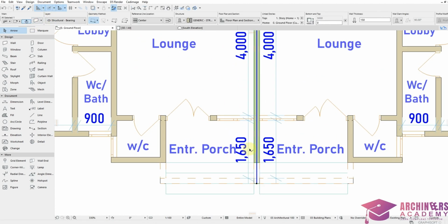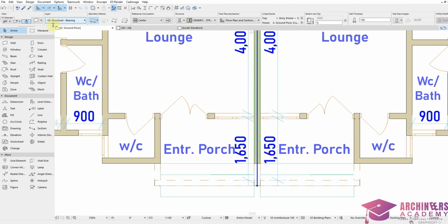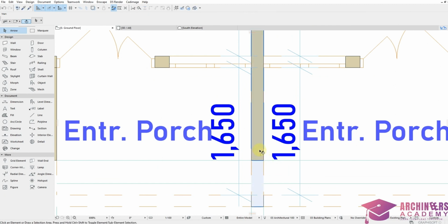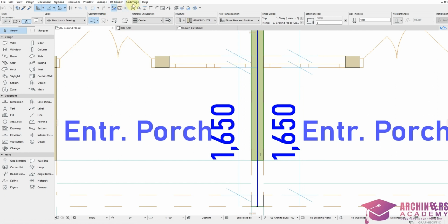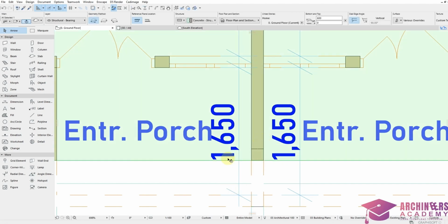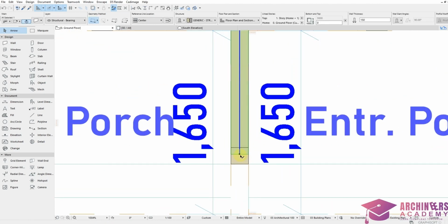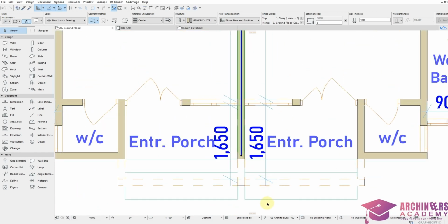If you love to save yourself, you can just use your trim tool or your split tool to separate this wall from this. You can actually split this wall so you have a separate wall for the empty window opening. For this design, you can split your wall, so you are free to have a separate wall.